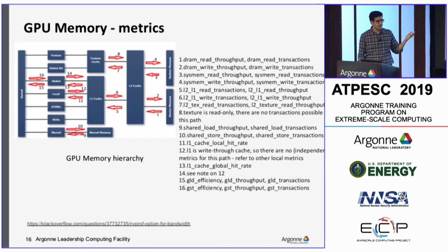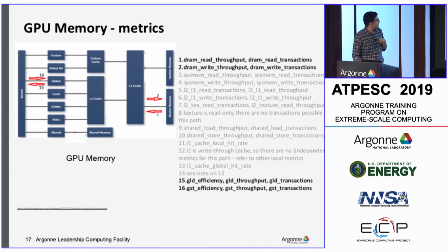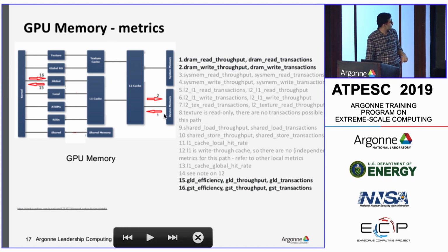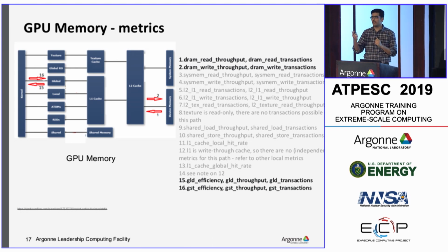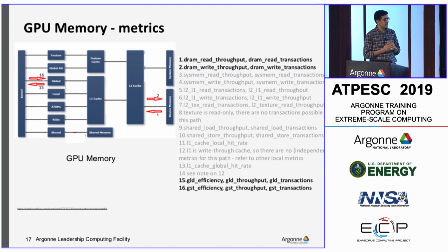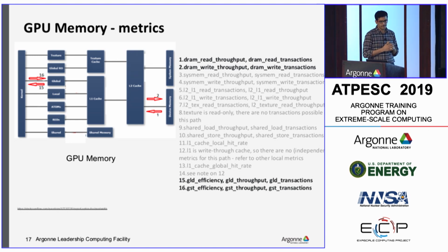If you're trying to abstract out this information, we want to focus on only two of these memory axes. If you see the arrows 1 and 2, as I said, these correspond to the accesses, the reads and writes through the external memory. That's you getting the data from the device memory, and that involves a lot of overhead when we are trying to have this large amount of data transfers. That could be a bottleneck when you're measuring the performance.